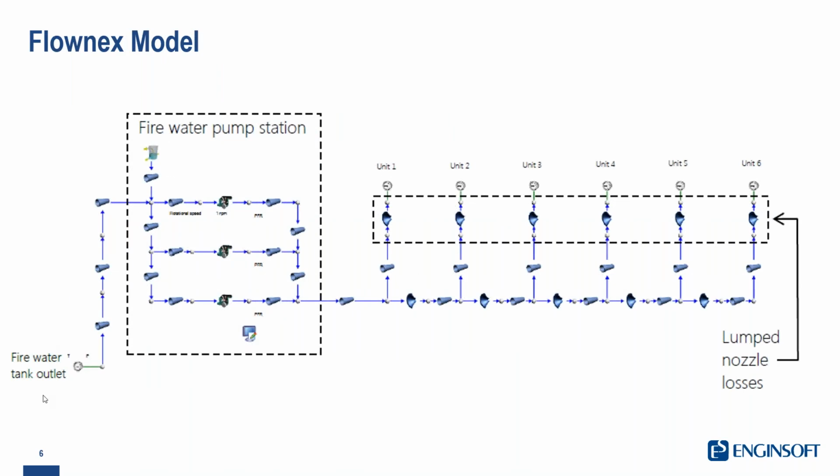So you have the water tank. Here you have the three pumps in parallel, and then you have all the network with all the orifices, so all the sprinklers that are used to spread out the water, so the nozzles. And the idea is the simulation of the startup of this system. So you have a curve that is regulating the RPM of the pump over the time.